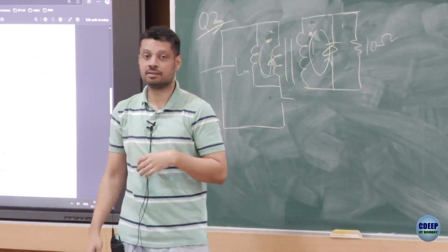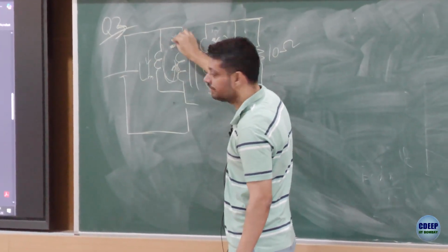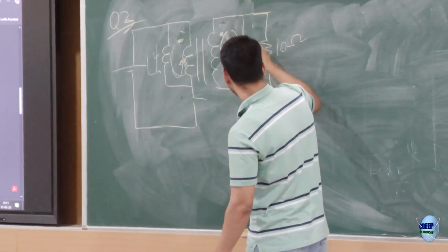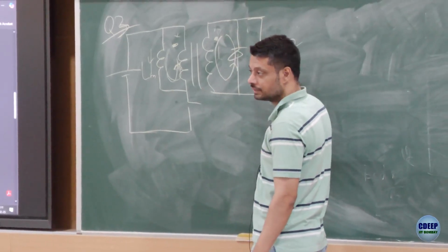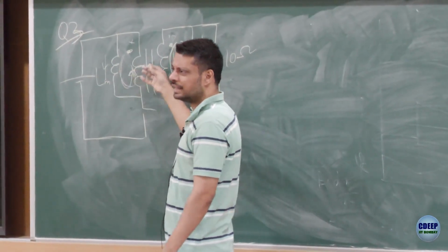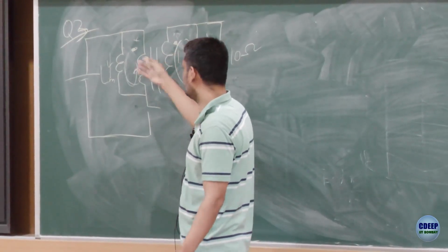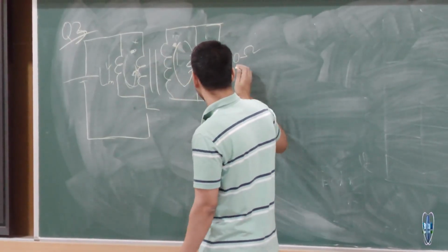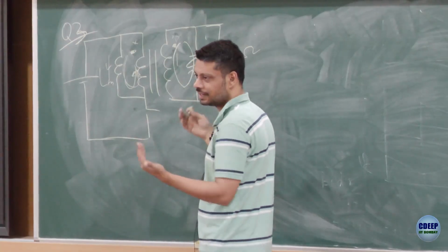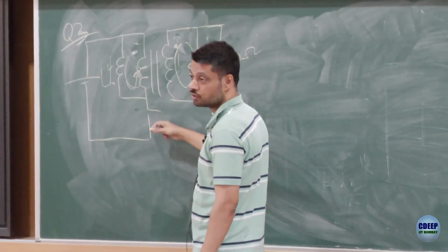Is that okay? So when this switch is off, this current will circulate in this loop, leaving the dot, it will enter the dot and it will flow through this diode. It can flow through the resistance also, but why would it take a higher resistance? It can just flow through an ideal diode, right? So this current will continue to flow. In reality, it would die down eventually because of small resistances here and there, but if it's ideal, it will probably continue to flow, but nothing will flow in the resistance. So as of now in the question, everything is ideal, right? So the energy transferred is only when the switch is on.